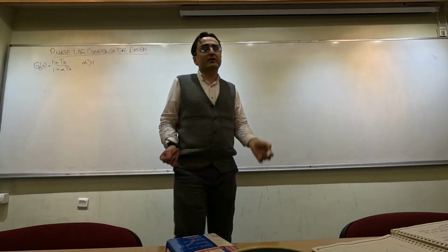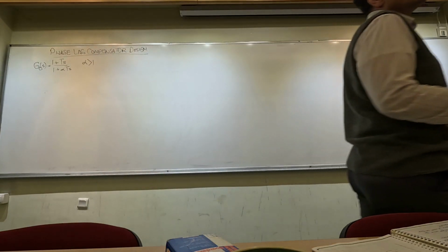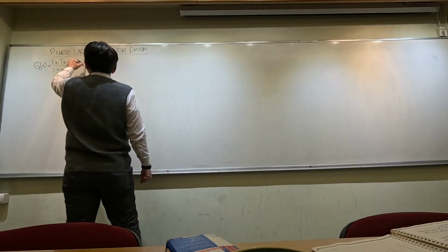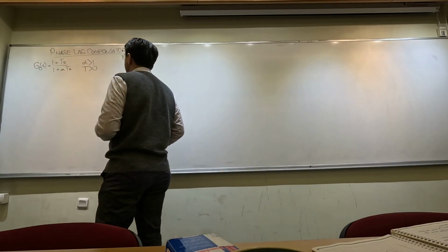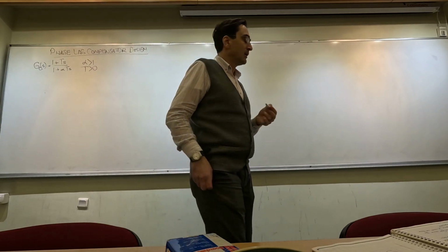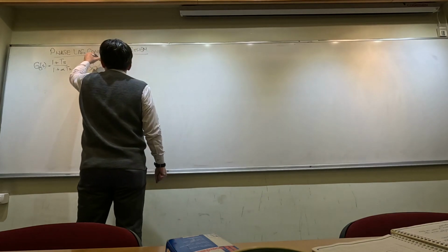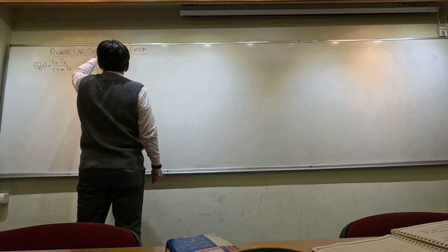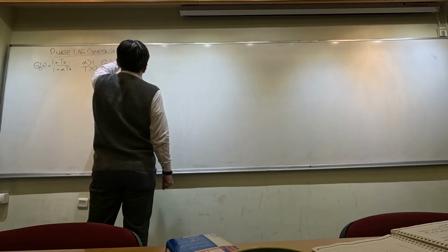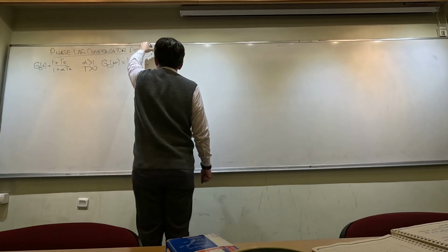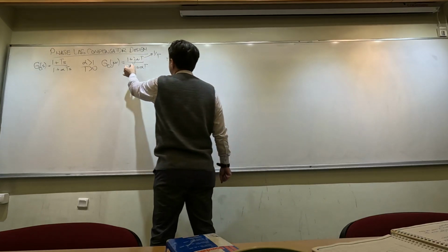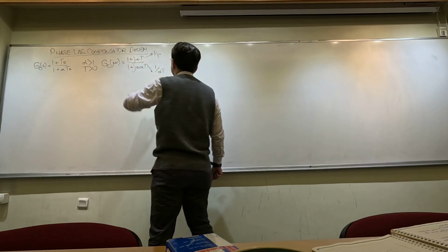In this case, the corner frequencies will shift their places. They will be swapped actually. Here T is still a positive quantity, and we would like to benefit from this phase lag compensator in a control loop. So I will look at the frequency response, GC of j omega, (1 plus j omega T) over (1 plus j omega alpha T). The corner frequency of the numerator is 1 over T, and the corner frequency of the denominator is 1 over alpha T.